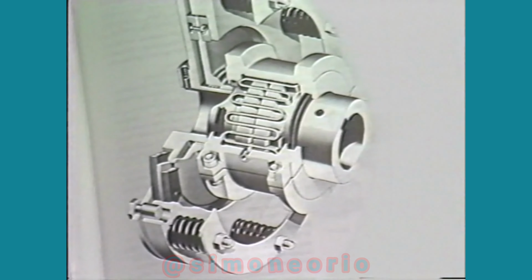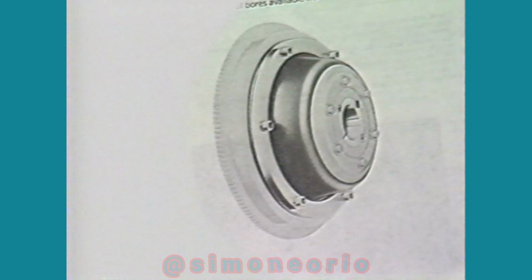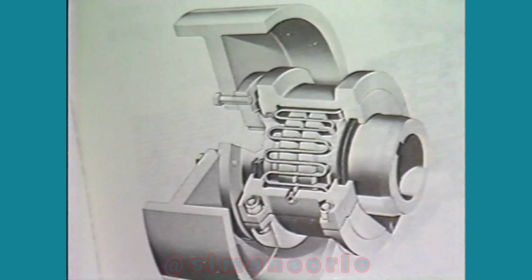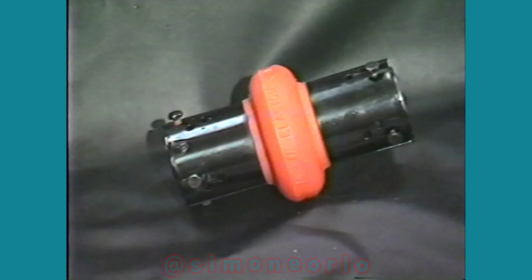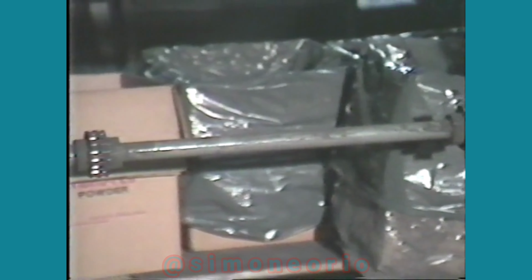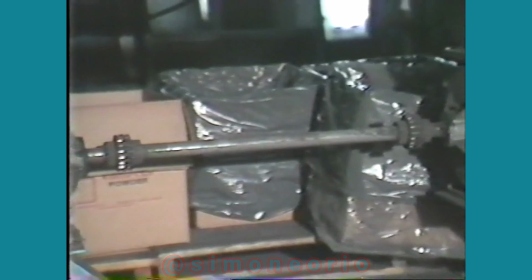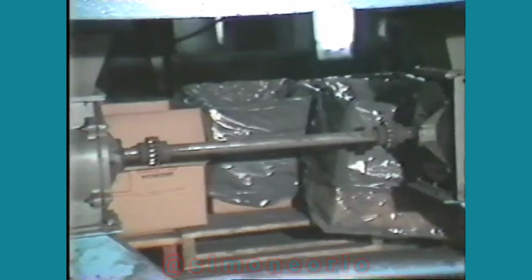Some of the special purpose shaft couplings are designed to provide overload protection, connect directly to engine flywheels, and to provide an auxiliary brake drum. Spacer couplings permit driven equipment, such as centrifugal pumps, to be repaired with minimal disturbance of the driver and the piping connected to the pump. Floating shaft couplings connect the driver and the driven shafts when the gap between them is greater than normal.